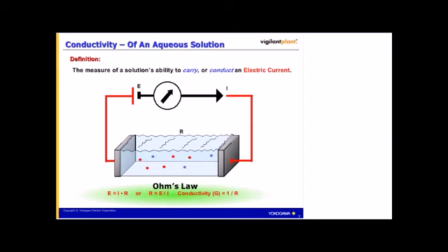Since we are interested in how well the circuit conducts that current, which is determined by how much resistance to the current flow there is, we must rearrange the equation to find out the resistance value by dividing the voltage by the current. Once we've figured out the resistance, it's an easy matter to determine the conductivity, as it is simply the reciprocal or inverse of resistance, and is shown in the third equation where G represents conductivity.